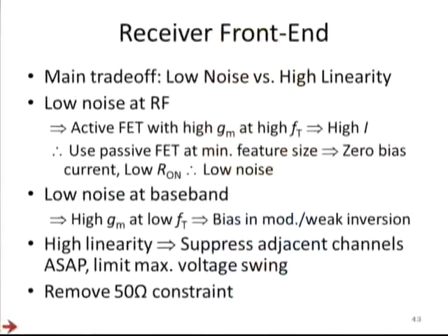Well, this is perhaps the most challenging of the presentations. How do you cut down power of RF circuits by 10 times when power seems to refuse to go down? Well, obviously it'll require radical changes to the way we do things. In the receive side, the main trade-off is between low noise and high linearity. We want to receive small signals in the presence of large unwanted signals. So let's look at some fundamentals here.